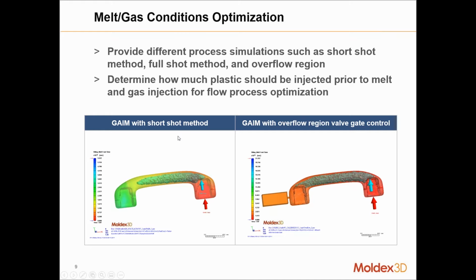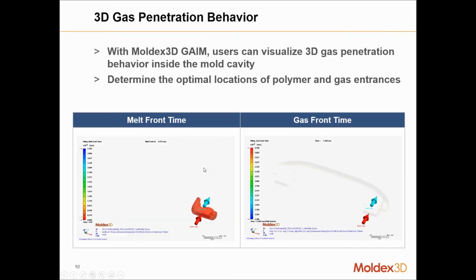injections. So that's what's known as the short shot method, and like I mentioned before, the overflow method is kind of the opposite way. So you'll have an overflow, you'll shoot into the overflow, and then you'll reduce gradually the amount of material that you're injecting until you get just the part shot, in which case you wouldn't need the overflow. You can always keep the overflow in your design, but once you optimize this process, you probably shouldn't need the overflow any longer.